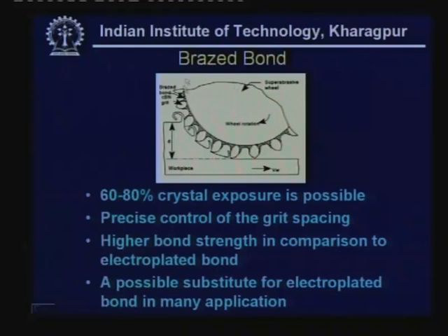Now, this is brazed bond. This is an innovative approach where we can still increase the crystal exposure, and with this crystal exposure a high material removal rate is possible. This is going to be a substitute for electroplated bond.